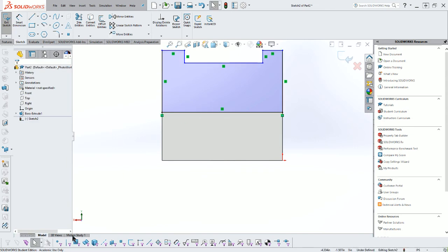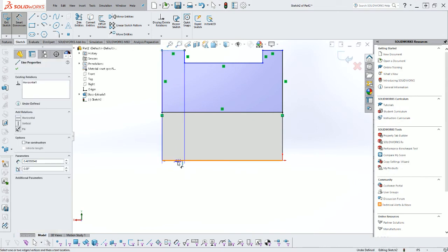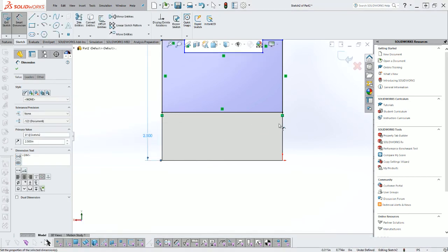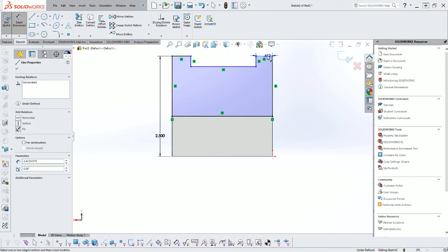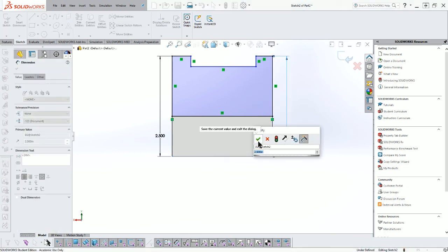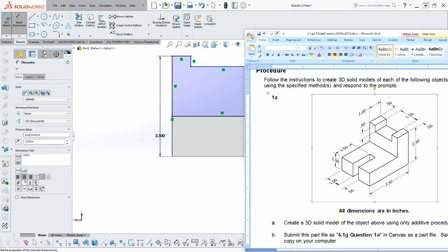and now I have to give it some dimensions. So to look back at my drawing, I can see that this is 2.5 inches tall total from the bottom to the top. So I can go ahead and use that dimension. I'm going to apply that dimension in here. I'm going to say both sides are 2.5. And for now, I'm just going to type it in twice. So I click on my top and my bottom. There are some other things I can do with collinearity and other commands to make that a little easier, which we'll learn later on. But for now, we're just going to dimension those 2 sides.